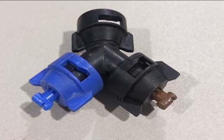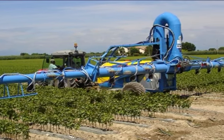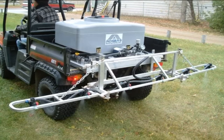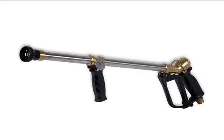Next is spray boom. This design consists of several nozzles mounted on a rod, ideally suited to row crops, and can be operated with foot or rocker or power operated sprayers. Next is spray guns. Spray guns consist of cut-off valve, extension rod and nozzle and can be trigger or hand operated. The spray pattern is adjustable from solid jet to hollow cone and they are most widely used for tall trees.